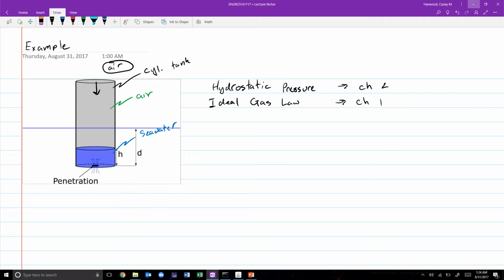All right. So the case that we're considering is this thing is sitting at the free surface and it has been given a dive command, right? It has just allowed air to escape and water to enter, but it has not yet begun to sink. It's at the instant before it actually begins to descend. So it could be thought of as a sealed cylinder except for this hole at the bottom, which allows water to enter and exit.